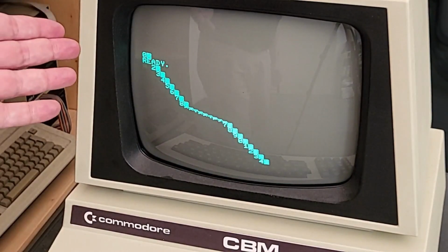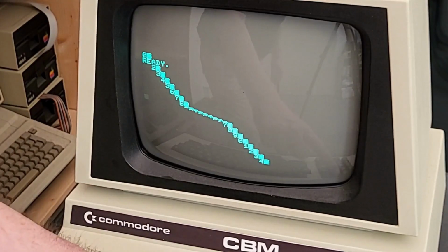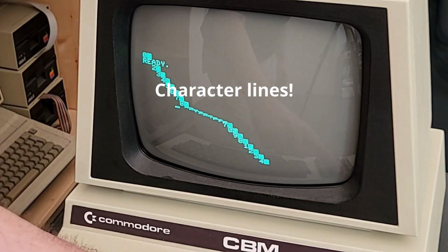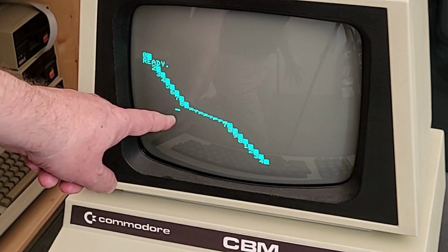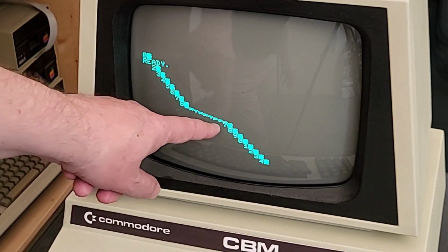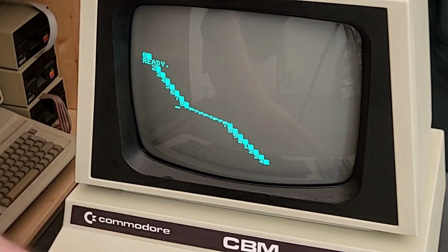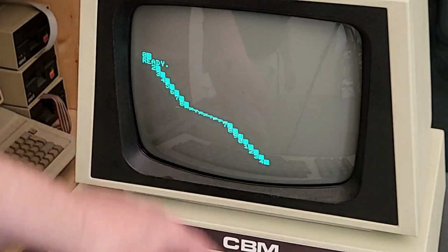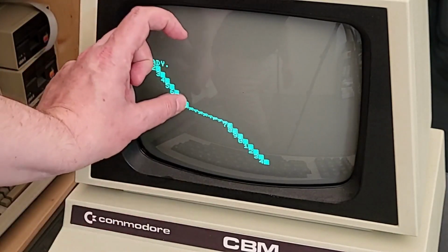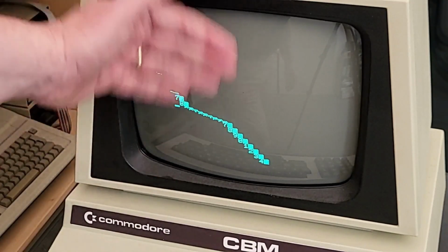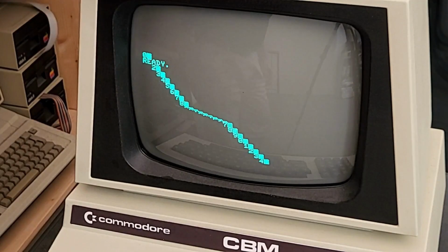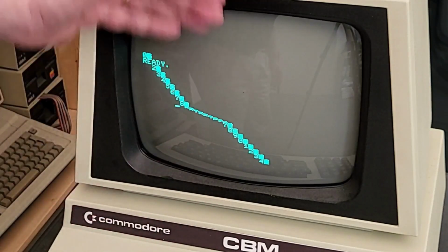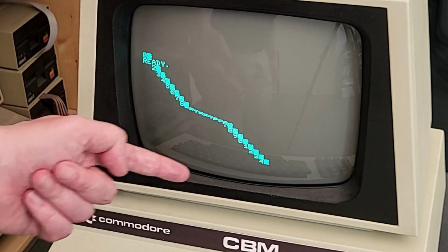So this is again an interrupt-driven program. And you can see here, those raster lines have the normal height. And then suddenly we have a number of raster lines that are only 2 pixels high. And the reason why this is working is because not all of those character lines have that height. So that could be used for a graphics mode on a part of the screen, and for the rest of the screen I have actually added a number of displayed raster lines. So in the end we get to the 400 raster lines that this screen geometry requires.